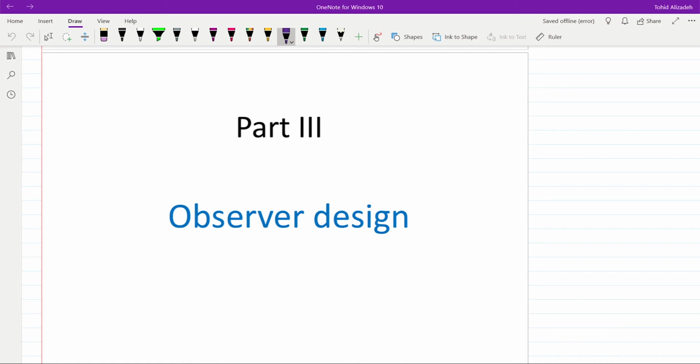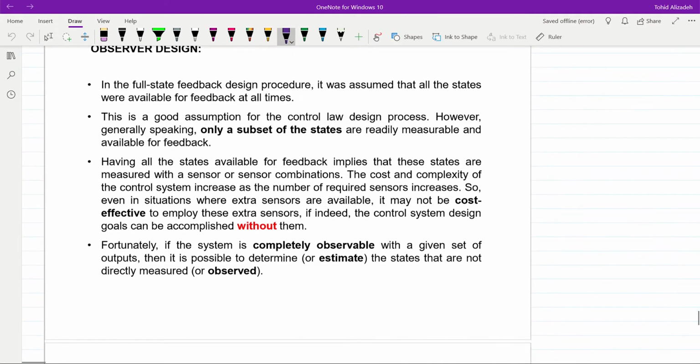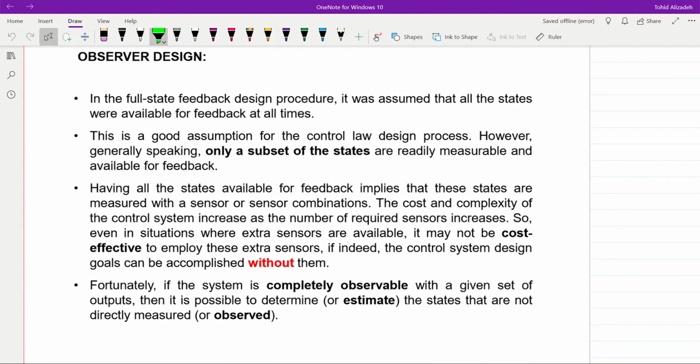Hello everyone. In this video lecture we are going to discuss observer design. When we considered the full state feedback design in the previous video, we assumed that all the states of the system were available for feedback at all times, because we were measuring them. We assume that they are available and we can measure them and apply the feedback gain and continue as we did. It's a good assumption for the control law, but generally we usually have only a subset of the states readily measurable and available for the feedback.